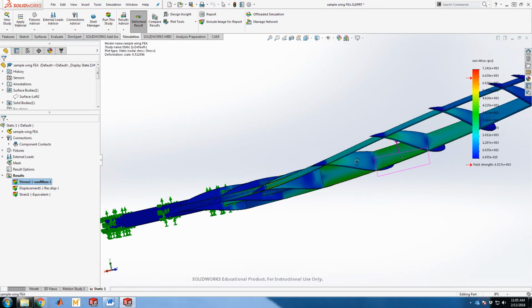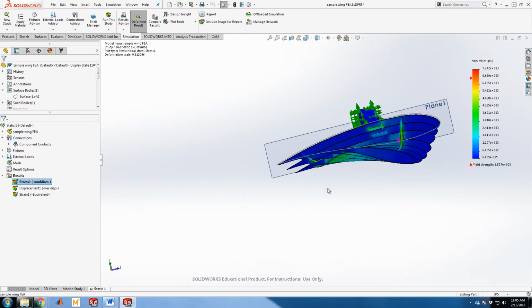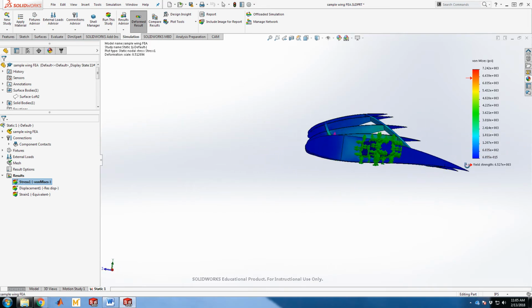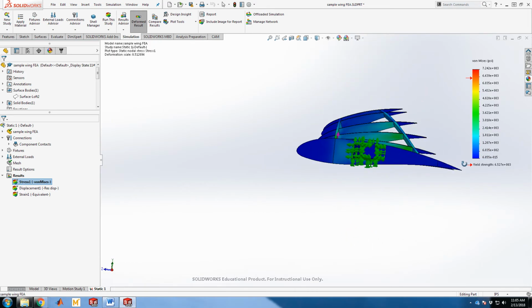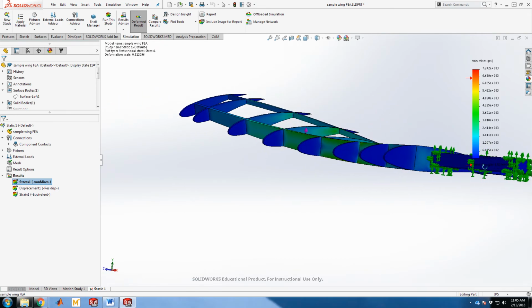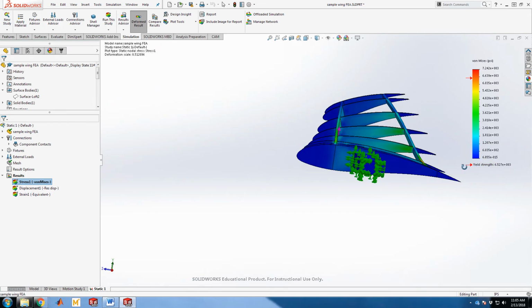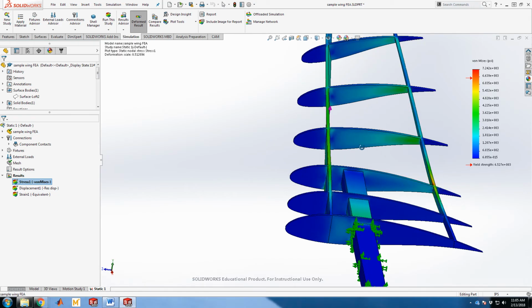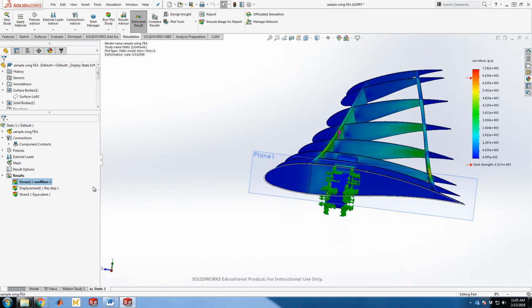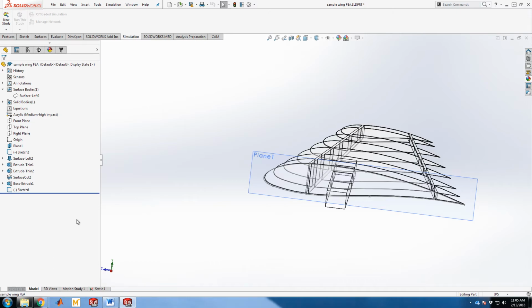But of course, we've only applied a 20-pound load. This is also telling us that torsionally, our wing is a terrible, horrible, awful design. The wing is twisting far too much. It's deflecting in lift, probably a little excessively, but we want to, in the end, move that aft spar up, which, hey, maybe we can do that.